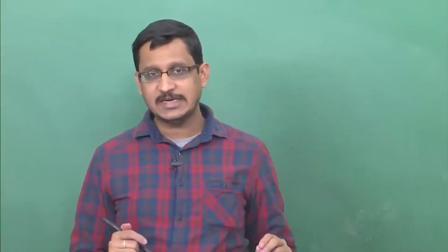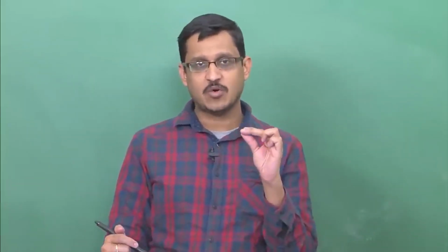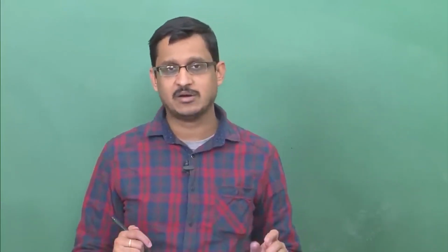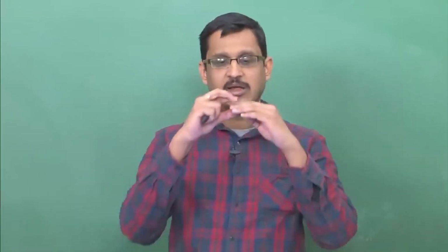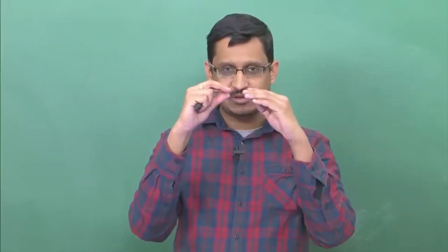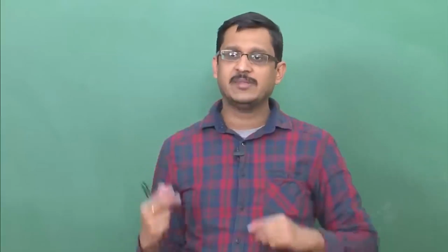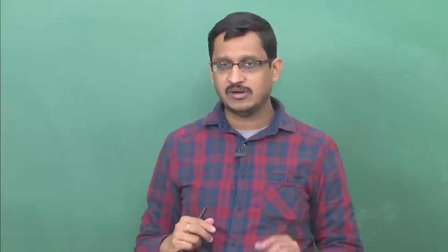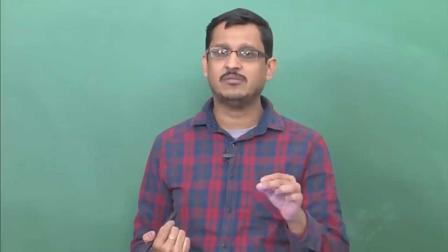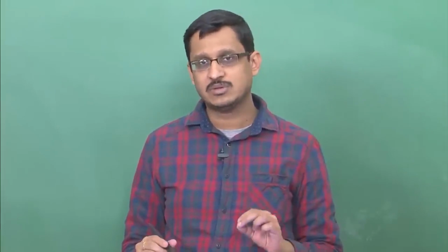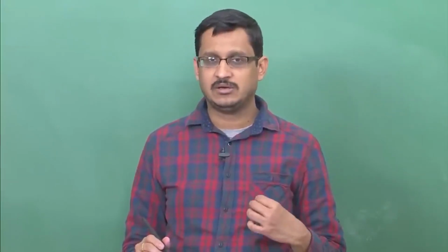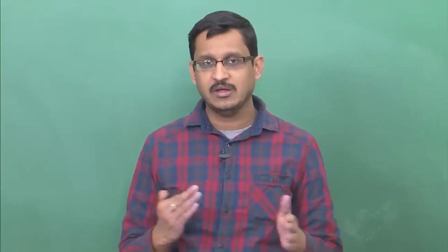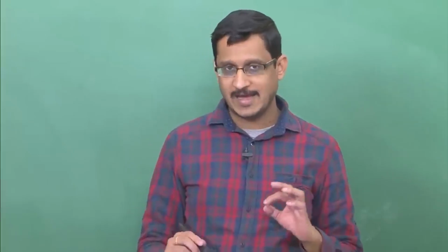depth. This skin depth becomes very small as the frequency increases, and if you operate this coaxial cable at around 100 or 200 megahertz, you will see that the current is confined to a thin walled area around the inner conductor, and similarly the current will be confined to the outer conductor in a very thin layer. This layer is around a few micrometers, and therefore this result is not much affected. So for the coaxial cable we did not really include that term, but strictly speaking one has to include it.